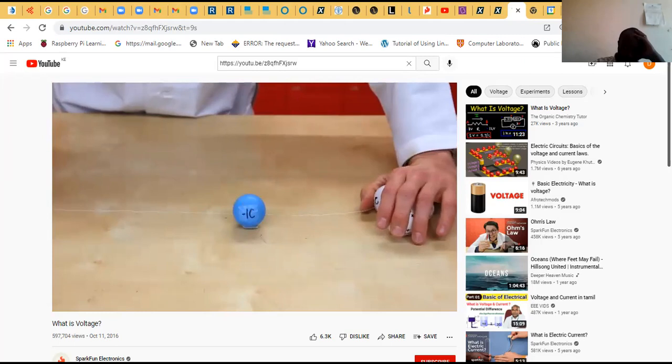As we defined earlier, voltage is the electric potential between 2 points. To calculate the voltage between their starting and ending points, we know that I did 30 joules of work to move the particles, and the total charge is 3 coulombs. So the voltage is 30 joules divided by 3 coulombs, which is 10 volts. We would say that the electric potential between these 2 points is 10 volts.